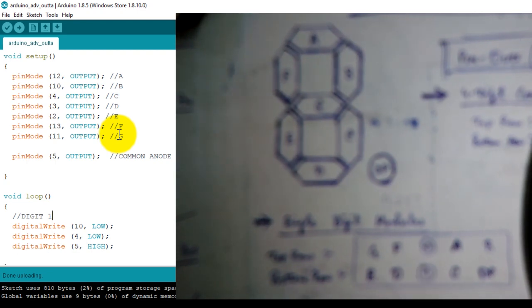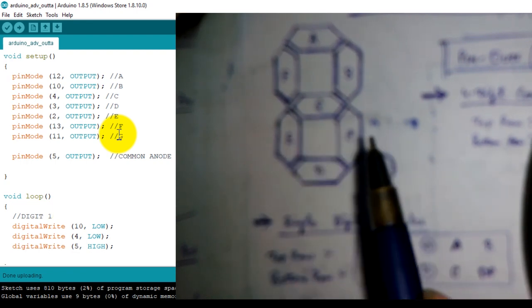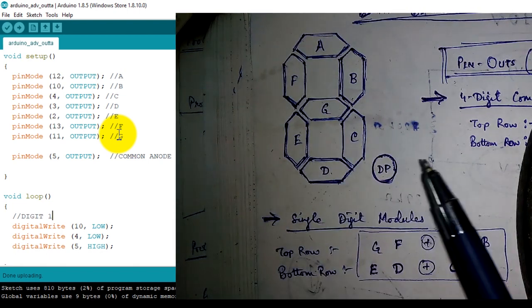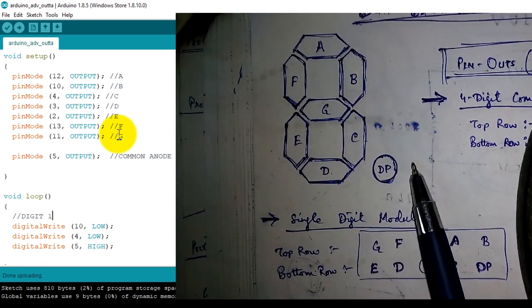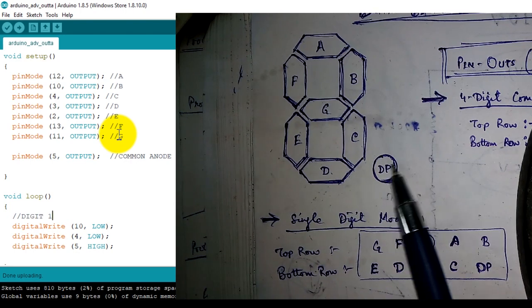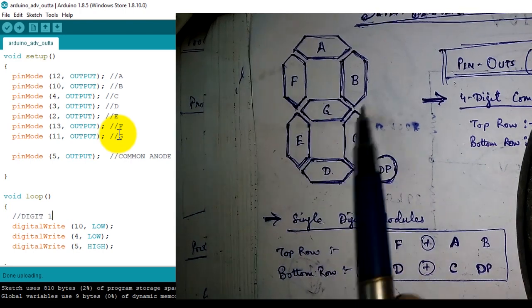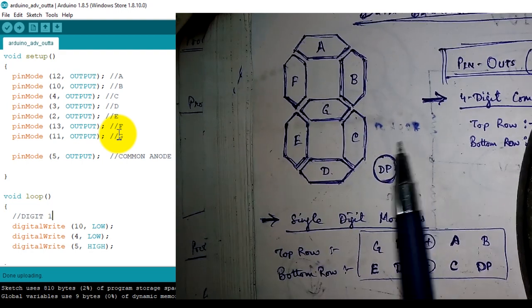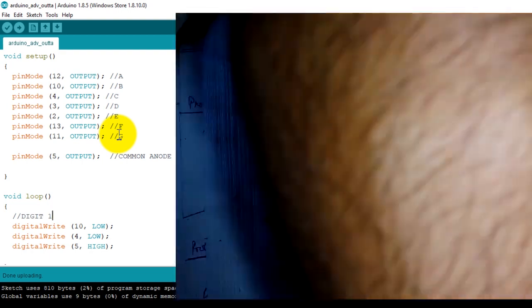So basically what I have to do is, when we are connecting all of our pins to our digital pins, that means they are by default grounded, isn't it? Everything is actually pulled low. So in my setup code I have to pull all these pins high so that nothing is pulled to ground. Okay, so I'm going to do that.